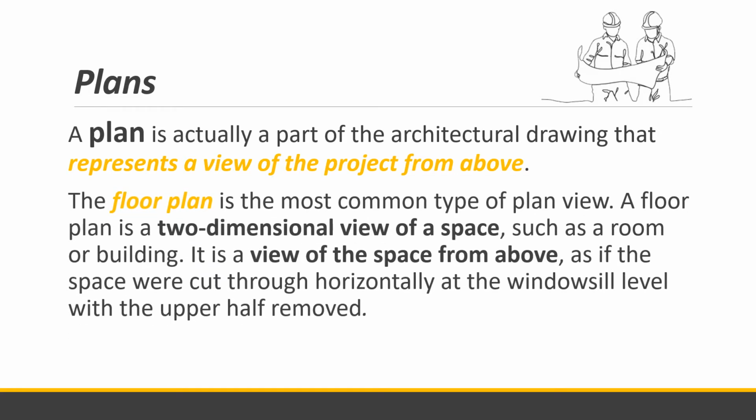One of these is the floor plan, the most common type of plan view. A floor plan is a two-dimensional view of space such as a room or building. It is a view of space from above as if the space were cut through horizontally at the window sill level with the upper half removed.